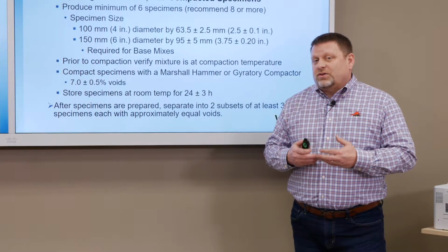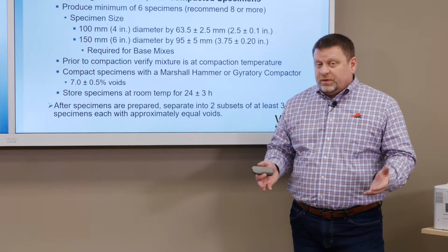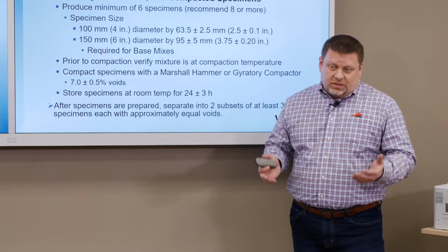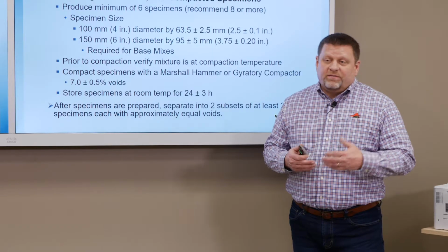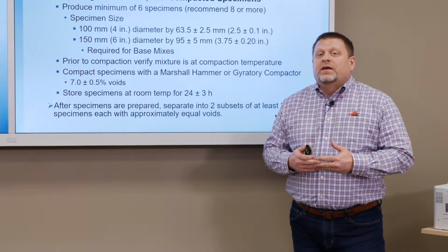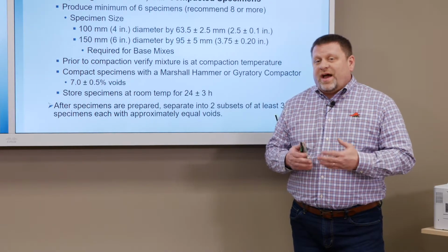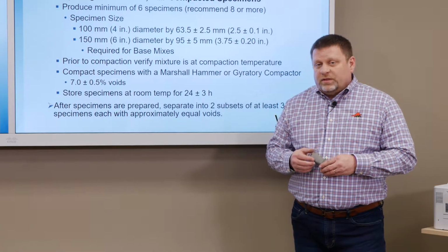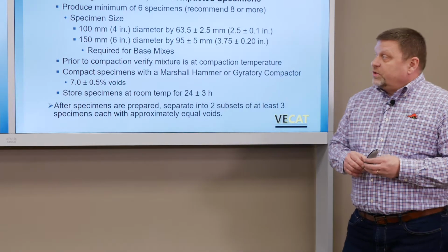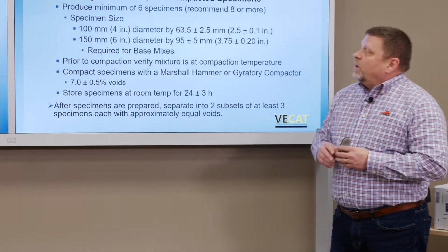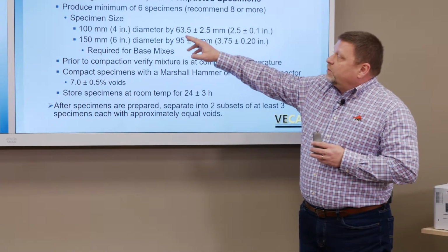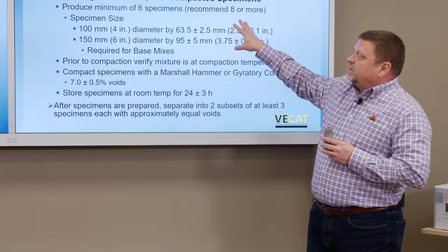The reason I say started within the first lot of a new mix production is the TSRs, you're going to find out, are multi-day tests, and depending on your startup, you may finish the first lot before you're done the TSR test, but you have to have at least started performing the TSR test on your material for this particular mix. All right, so as I'm saying here, your material is plant mixed, but lab compacted specimens.